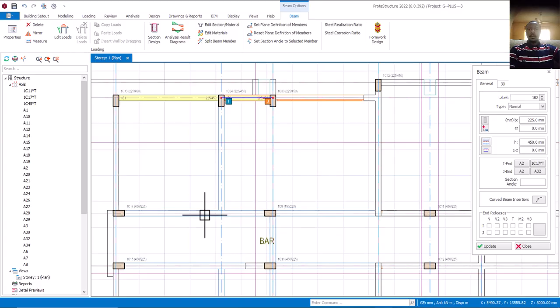Is that okay? So I'll come here now, also click on this, right click, then offset up, F2, by 225. Enter. Then come here, delete. Alright, come here also, finally right click and offset and bring it down by F2 and press minus 225 and then enter.